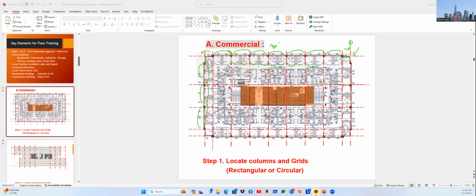So there are many factors. Usually we need to consider and coordinate with the design architect team based upon their interior use, exterior outlook, and all the exterior curtain wall modules. But basically, for a high-rise super tall building, what you can guess from this plan is that there is no interior column. I'm saying no intermediate column inside here, right? No interior column, typically, in the major workplace.